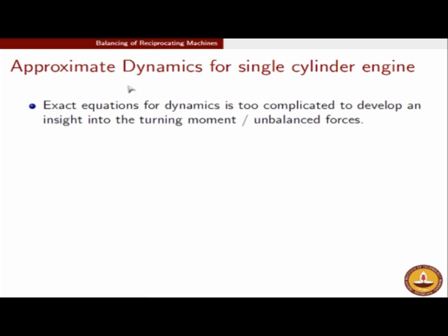We are now trying to determine the approximate dynamics for a single cylinder IC engine. The exact equations for dynamics are too complicated to develop an insight into the turning moment and the unbalanced forces. The equations can be formulated, it is a big set of equations, but with that we are unable to fathom how exactly the unbalanced forces behave. Is it harmonic? Does it have a simple formula? On what factors does it depend? These questions are not easy to answer if we look at that 8 by 8 system.